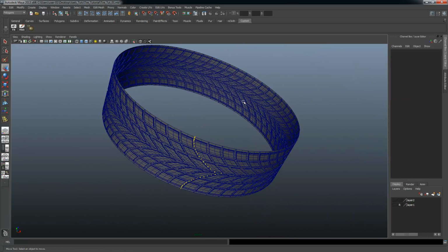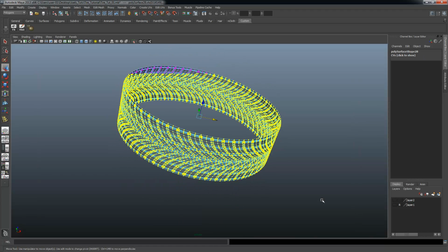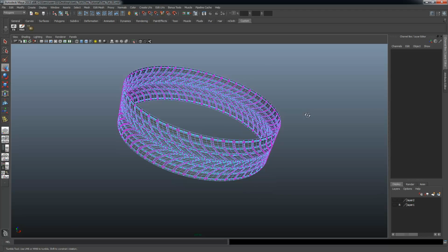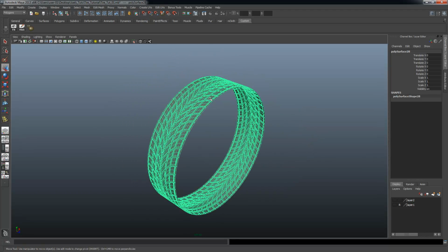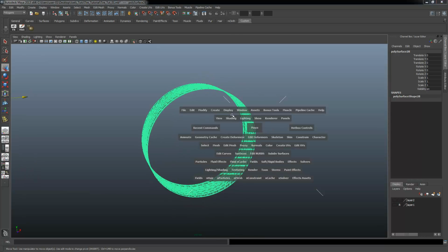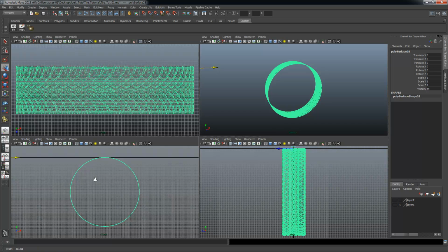Alright, so now what I'm going to do is I'm going to select my mesh. See how we kind of have these stuck vertices again? I'm going to try to select all and then deselect. That's kind of what you have to do sometimes. Sometimes that doesn't work, and you actually have to export your mesh as an OBJ, but I don't have time for that right now. I'm trying to keep this thing around an hour.